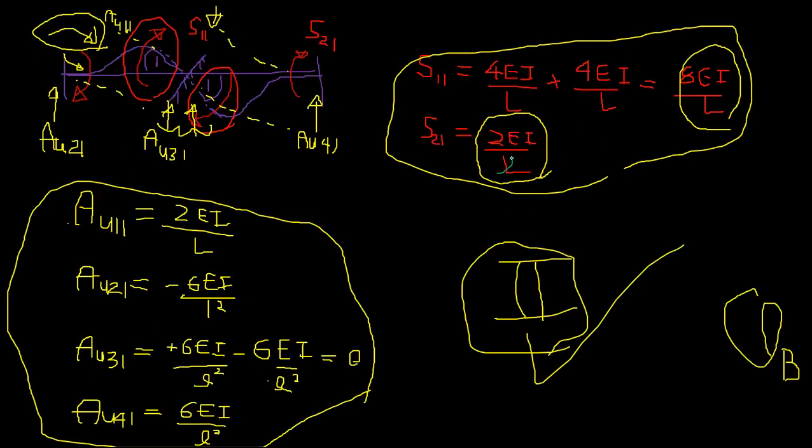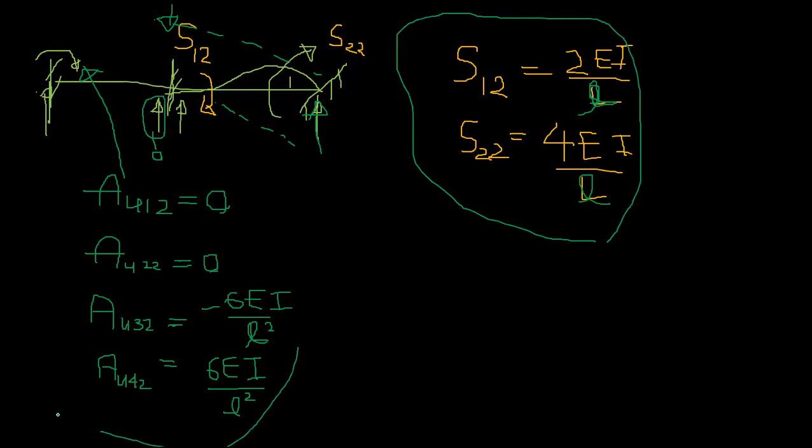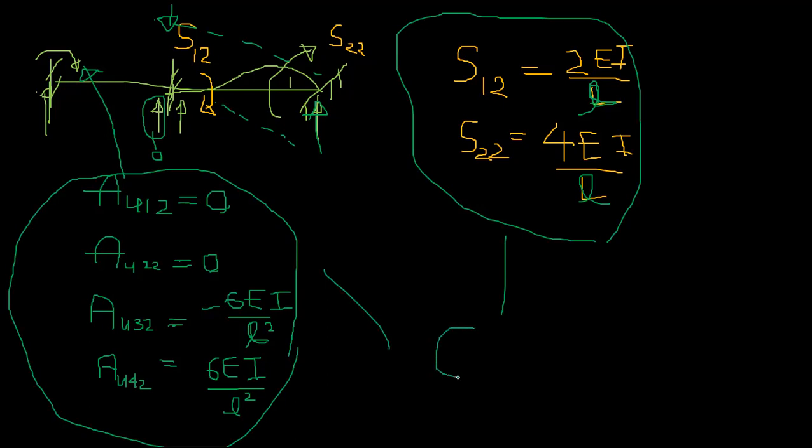Right? Yes. So good practice is you take only the magnitude from the appendix and you determine the sign or the direction according to your sign convention. These are the bending moments and actions for a unit rotation, so you need to multiply everything by theta c. Then that's done. The third step is okay,